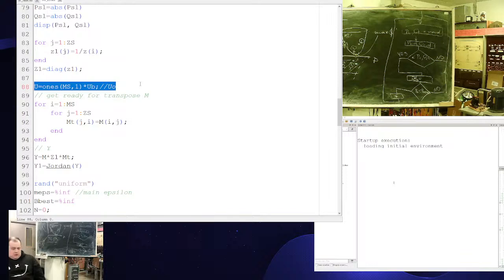At first hand, the higher the voltage, the smaller the transmission losses. But on the other side, if you raise voltage, the losses in the steel of the power transformer rise drastically. So in reality, good power companies perform research on the optimal level of voltage in the network.